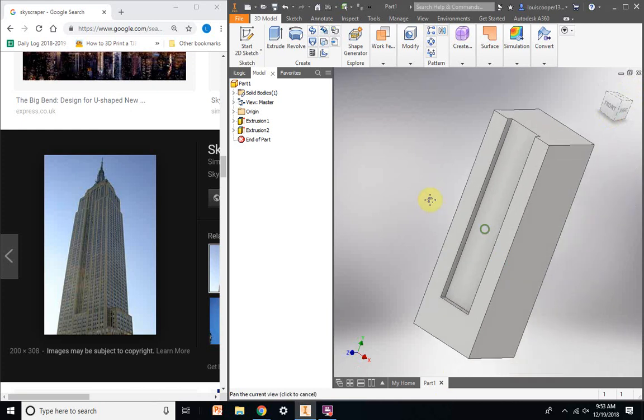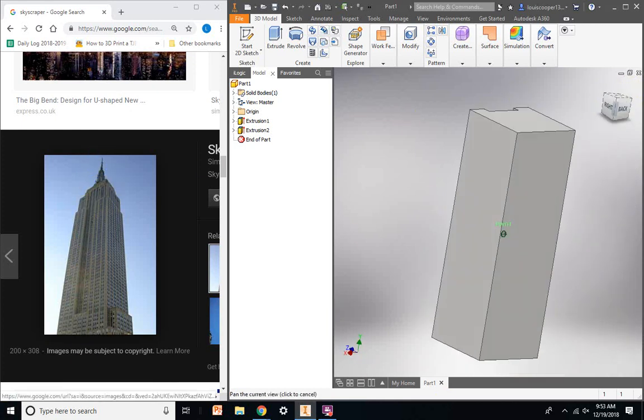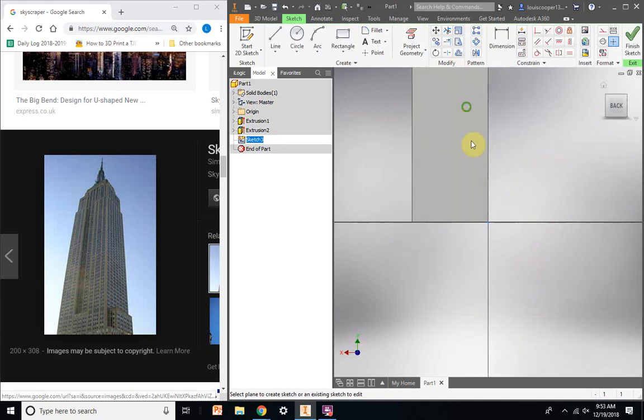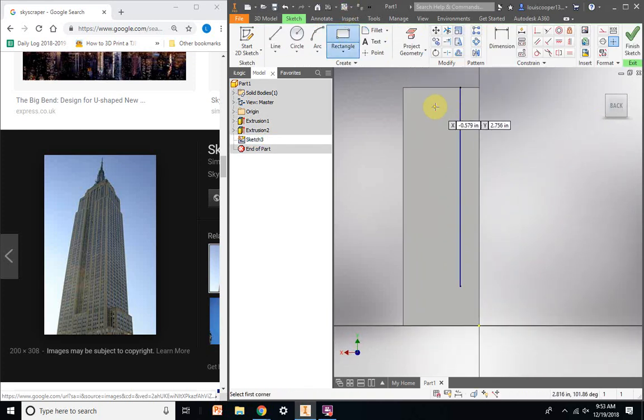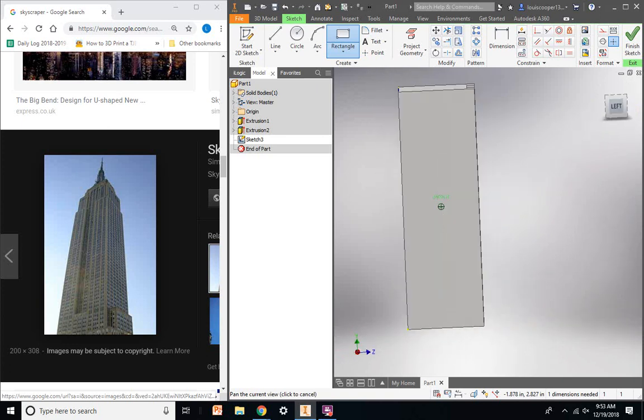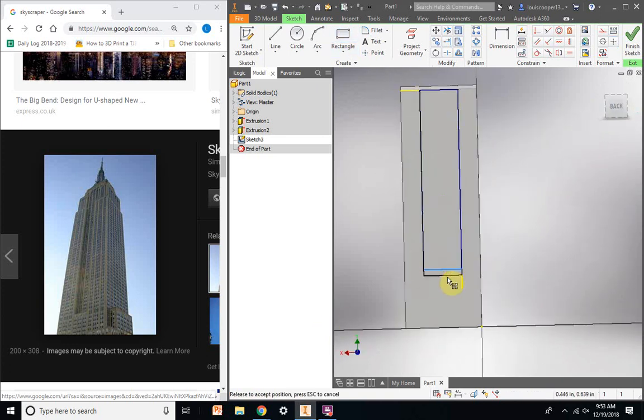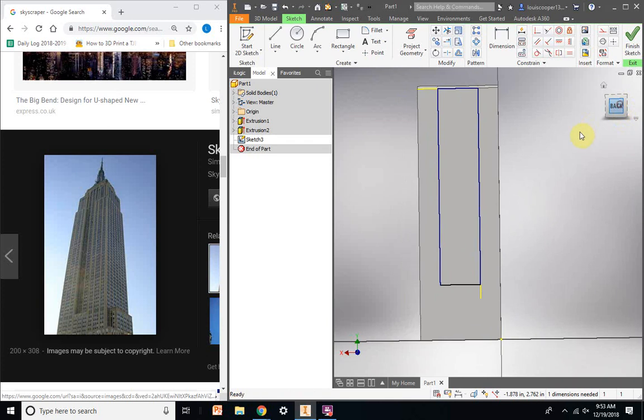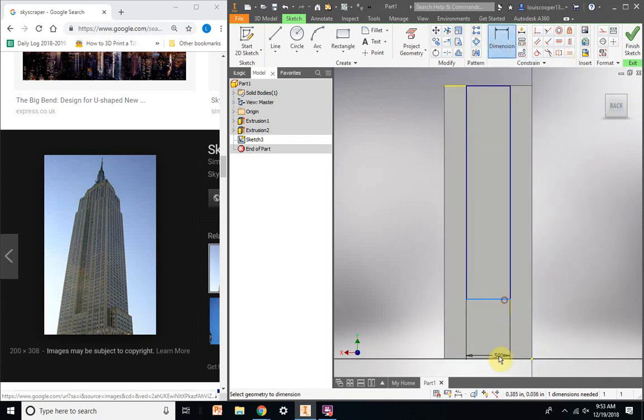So that's the beginning of my cut-in right there, okay? And again, I'm going to do that on the back as well. So again, I'm going to draw my rectangle here somewhere till about, I don't know, there. You can always look and see. If I really wanted to be smart, I would have put a dimension from here to here. That way I know it's the same, and I'll do that for you. So I'm going to make it 0.65, okay? And we're going to finish this.